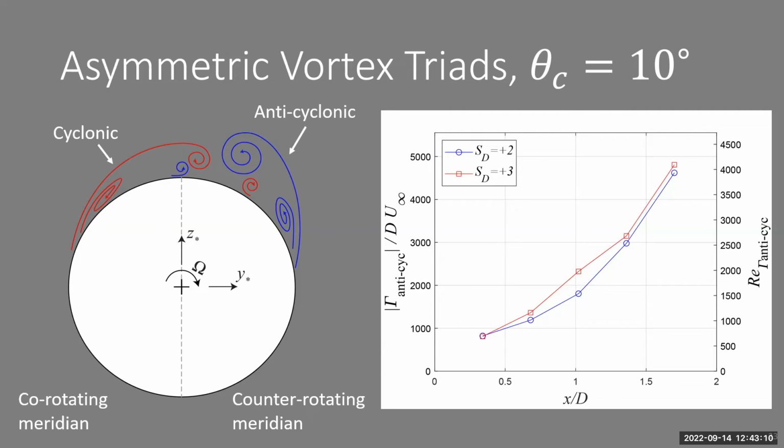That strength is increasing. Furthermore, with an increase of angular rotation rates, we see a slightly upward shift of those values. That's because in the region between the anticyclonic primary vortex and the cone, there's a co-flow region. The direction of the boundary layer is rotating in the same direction as the bottom portion of that vortex, so it's feeding into the vorticity of that primary vortex.